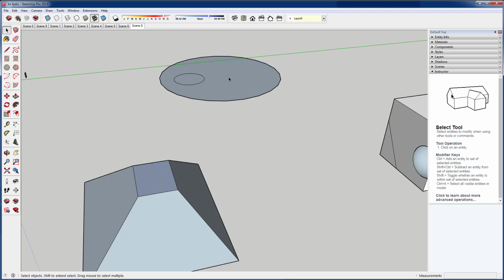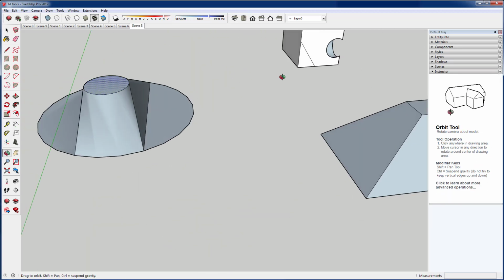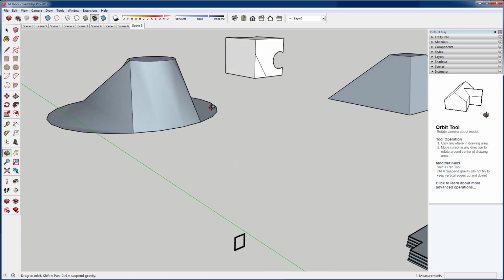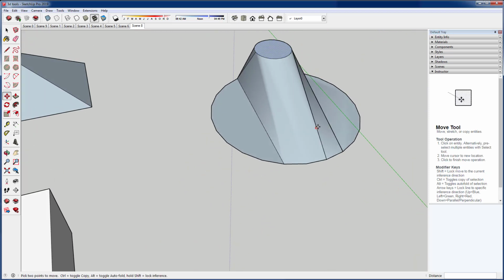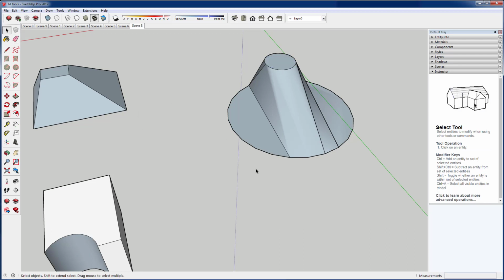So if I were to do a selection of that smaller circle and then use the move tool and hold down the Alt key when I drag it up, you can see I'm going to get some interesting auto created surfaces from that selection. Okay, so sometimes it gives you some unusual results, like in this case, but if it were something that you had some kind of strange roof line or something along those lines, this might be one way to create the edges that you might need.